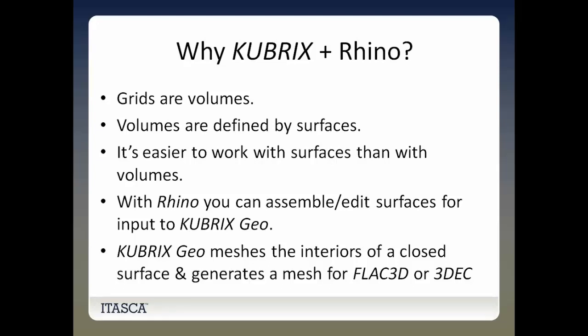You edit the surfaces, and you create one nice surface that you hand over to an automatic mesher, which understands what this surface is, what the interior of the surface is composed of, and fills the inside of it with a mesh. That's the sequence of operation. Surfaces are defined in some CAD tool, Rhino. Once the surface is identified and clearly defined as a closed surface, which may have multiple volumes inside it, the automatic mesh generation program understands what we mean by mesh here and meshes it.